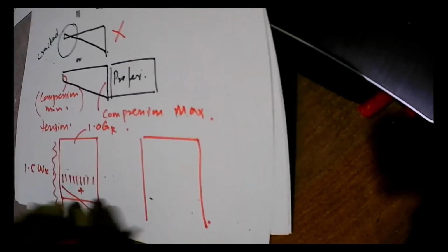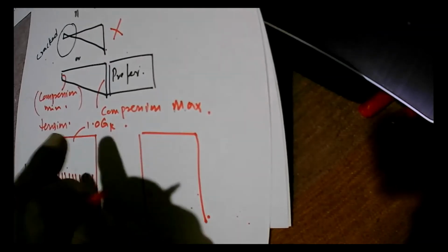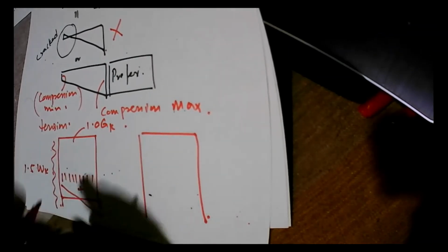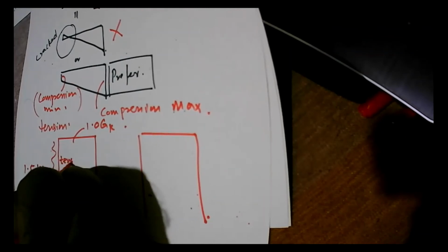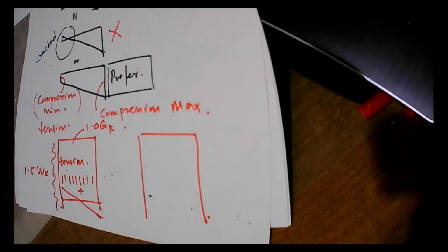there's a chance of getting this particular stress distribution. So we actually want to see whether this occurs. So what we do is we apply the maximum wind load on this side and the minimum vertical load. And these are applicable only to the tension side, but not applicable to the compression side. For the compression side, we have to make sure we get 1.35 Gk and the maximum load 1.5 W. So this is how you have to look at it, and this will give the compression.